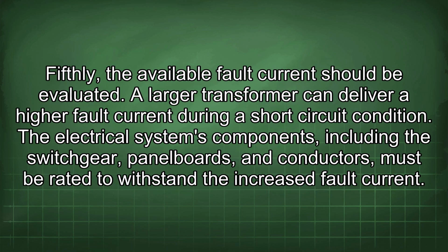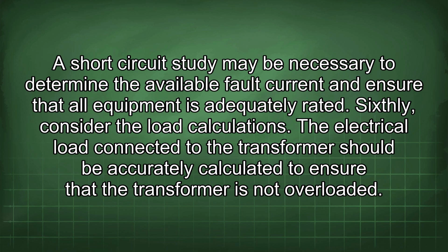Fifthly, the available fault current should be evaluated. A larger transformer can deliver a higher fault current during a short circuit condition. The electrical system's components, including the switchgear, panel boards, and conductors, must be rated to withstand the increased fault current. A short circuit study may be necessary to determine the available fault current and ensure that all equipment is adequately rated.